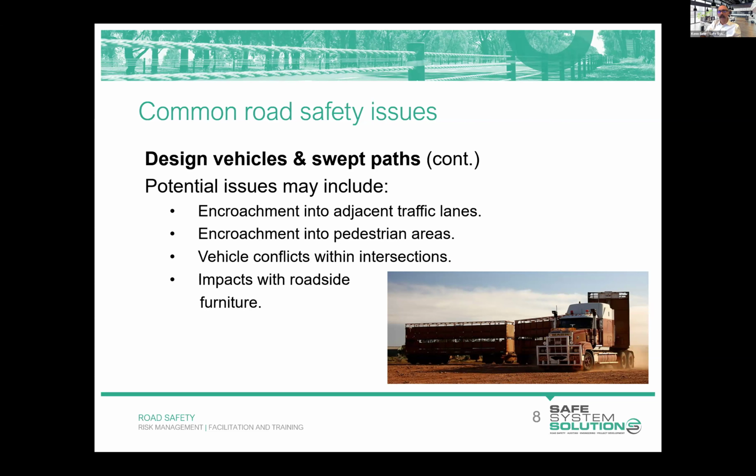And then you've got those weird ones like buses and then articulated buses, and these sorts of things. So where do you get the information? And as an auditor also, what is your requirement in this space? Are you doing the swept paths? Are you actually getting an auto turn and running those yourself with the CAD files, or are you just requesting them, or how do you go about that?